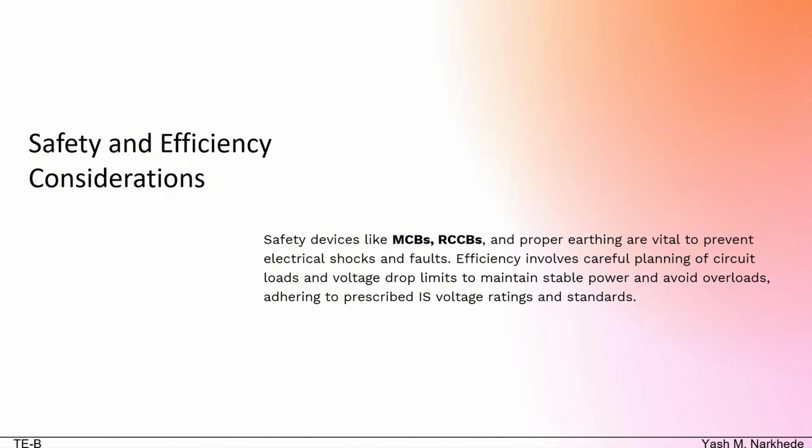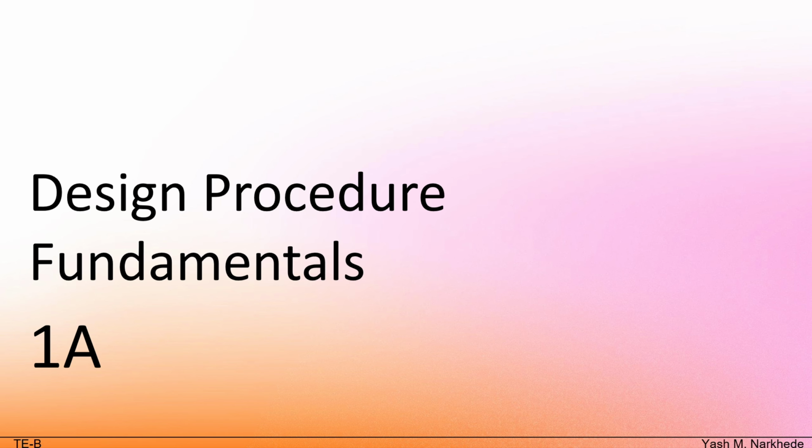Safety and efficiency are both equally important. Devices like MCBs, RCCBs, and fuses protect against fault and shocks. Efficiency comes from proper wiring sizing, minimal voltage drop, and balanced load distribution across circuits. Now first we'll see the design procedure fundamentals.